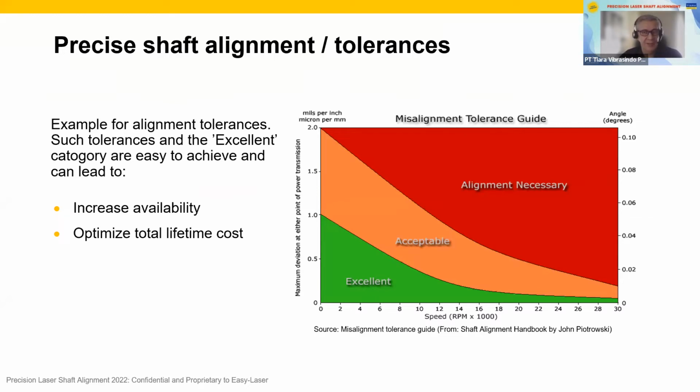If the speed is greater, the damage will be greater as a consequence. So the guidelines, tolerances and norms that we apply all refer to some kind of relationship between an allowable gap or misalignment per certain speed of the assets.